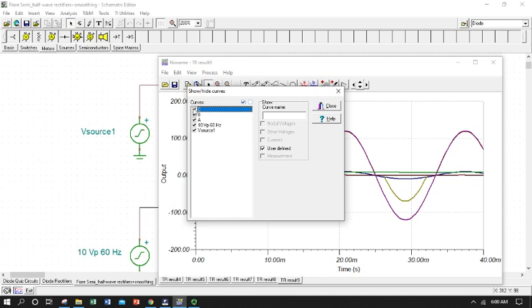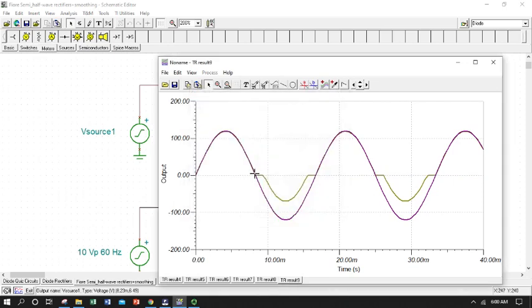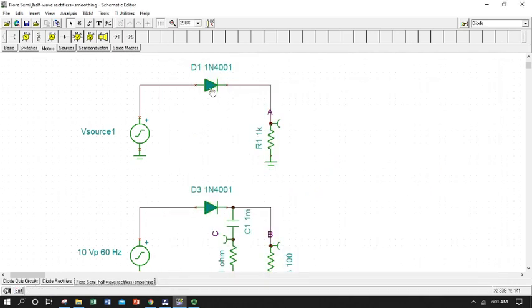I'm going to hide all the curves I don't want before I look at anything. And oh my goodness, I'm on the forward cycle. I got exactly what I wanted. My input cycle and my voltage over my load is almost superimposed, but good heavens, I'm not getting rectification anymore. That negative cycle is starting to break through, and so the diode is no longer stopping. It's no longer acting as an open with that higher applied voltage. So what in the world could have happened to cause that?